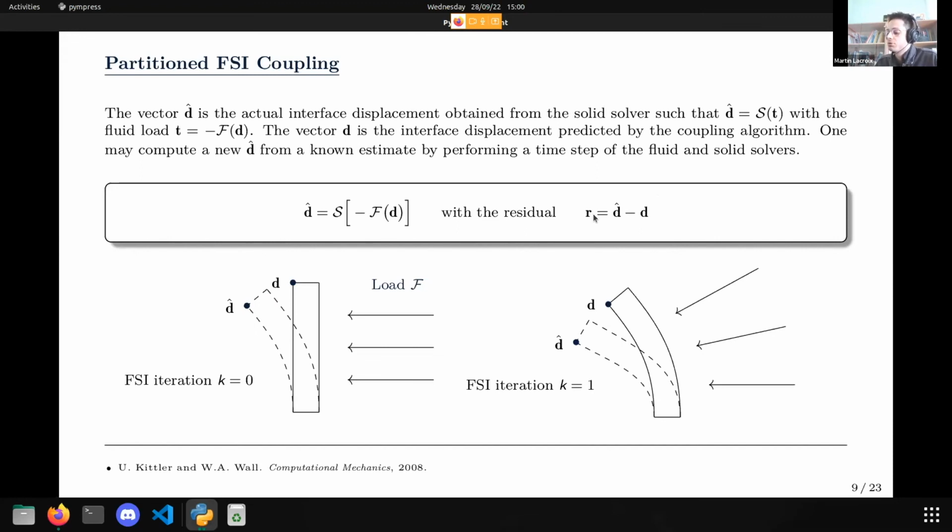And this is why generally what we want to do is to remesh only when needed. So ideally, you may compute some kind of distortion factor in your mesh. It can be local or global, to know exactly when you need to remesh or when you can continue without changing the topology of your mesh. But from one time step to another, within the PFEM solver, there is no remeshing. And so the convergence is like the classical finite element method. Between two remeshings, nothing has changed from the classical FEM, so the convergence is exactly the same.